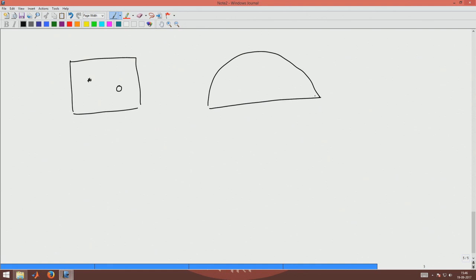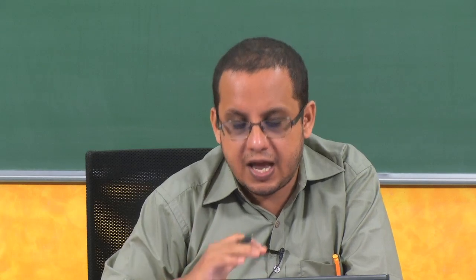If it is a semi anechoic chamber, you may put the source and the receiver exactly at the same location, but just the domain under consideration is different. So, the Green's function associated with the domains will be different and it will capture the room under which you are doing the acoustic analysis.